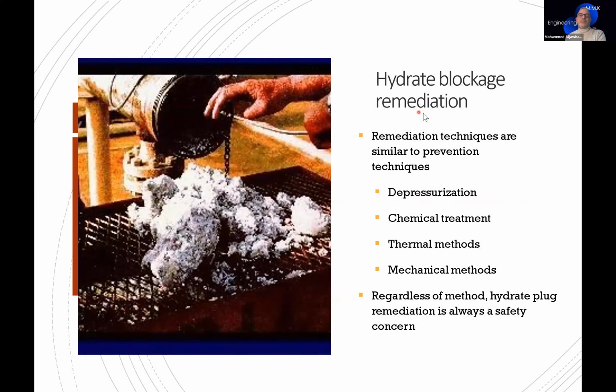So for hydrate blockage remediation, maybe depressurization, chemical treatment, or thermal methods. So it's regarding what we need and what we have in our system.